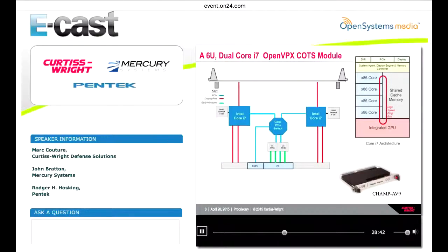What's new with this module is that you actually can render displays, not just use the GPUs for accelerating math with OpenCL, but we have customers, for instance, that are using a module like this to actually render displays in ISR systems to operators, and those red lines represent 6 individual displays. So there's a lot going on here. This is a very complex card, 32-layer. It's really a feat of engineering, and it's fully ruggedized so that whether it's air-cooled or fully conduction-cooled, this module can go in some very rugged ISR payloads.